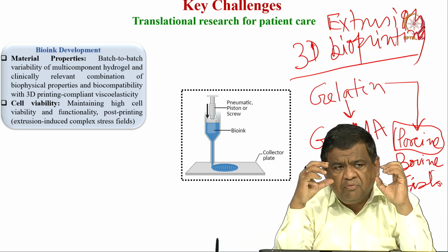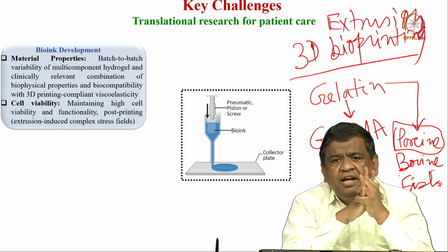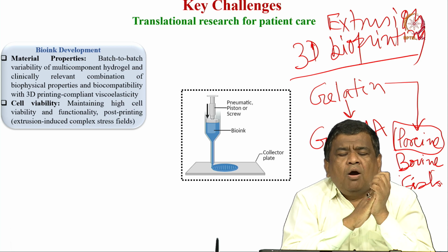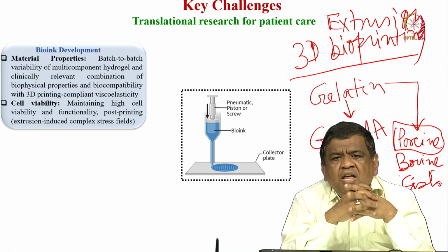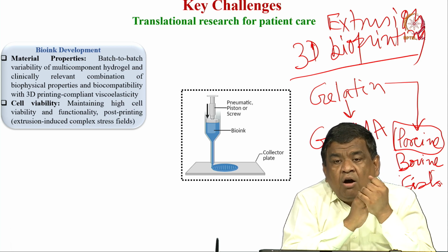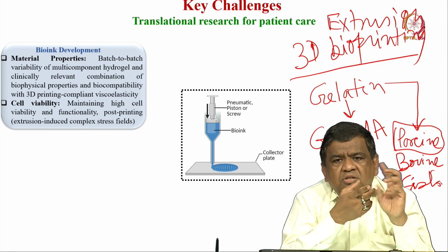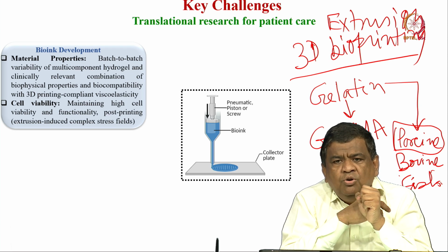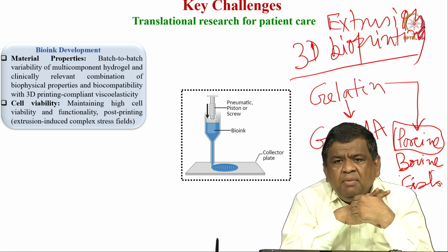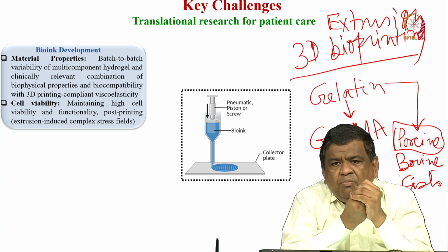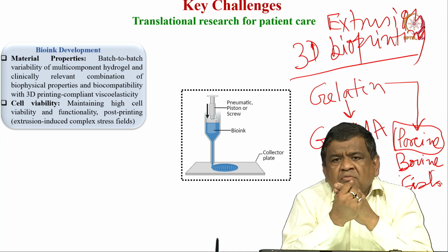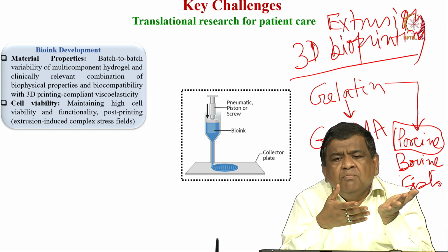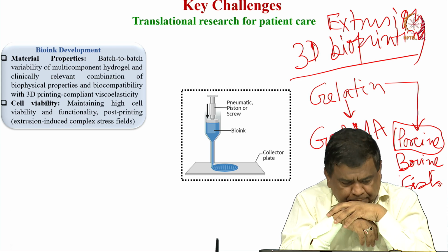So, from the same porcine source, porcine cartilage, when you are making this GELMA, there is a problem of reproducibility or variability, either in the degree of substitution when you produce GELMA, or in the viscoelastic properties of GELMA, like the G prime and G double prime values, and how temperature sensitive those properties are, because all those things are important for 3D extrusion printing.